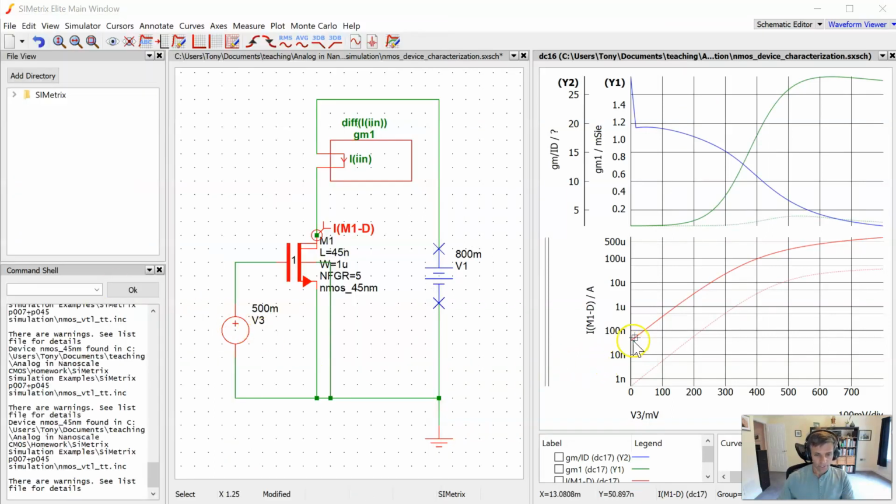So again, just eyeballing it here, we see that the drain current increases by about 1 order of magnitude, a factor of 10, with a VGS increase of about 100 millivolts. And if we plug those numbers into a calculator, again assuming room temperature, we again get a subthreshold slope parameter N somewhere around 1.75, 1.8, a little bit lower than what's predicted by this value up here.